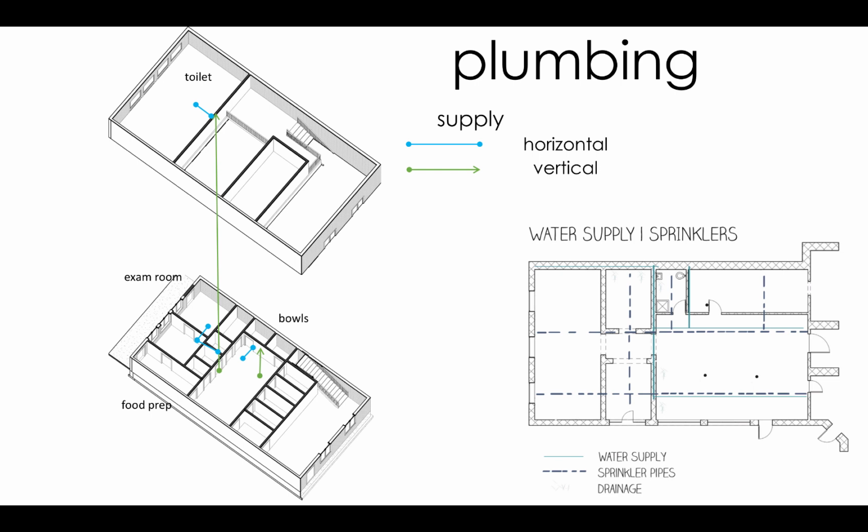the waste pipes. And then you want to make sure that the wall that you stick the waste pipe in and the supply lines line up. It's particularly important for waste lines because they're just much thicker pipes. But even supply lines, it is nice if the walls line up. Not a complete disaster if they don't, because you can run plumbing above the ceiling or below the floor or in the floor. And here's an example on the lower right of just a floor plan view.